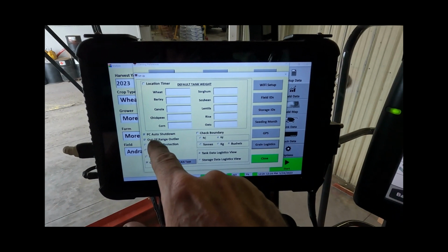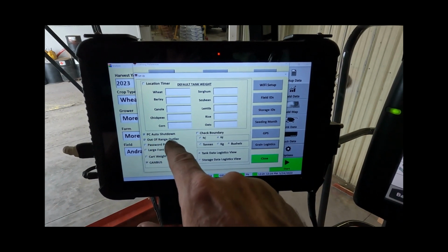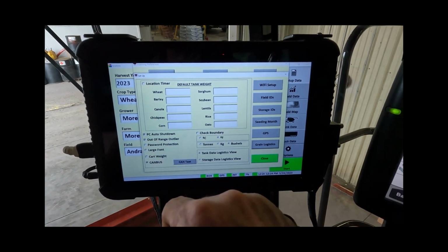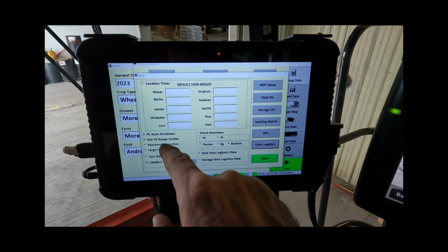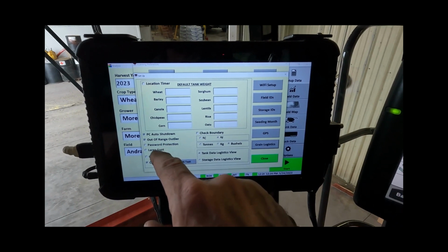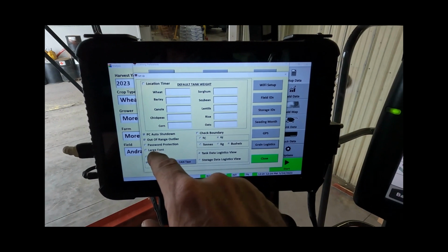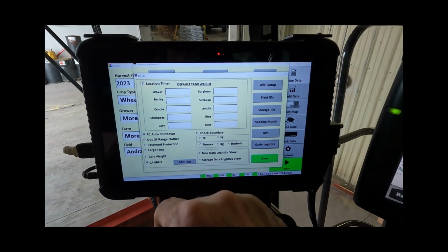This feature is used to detect when a predicted result for protein or moisture or oil is detected, and this will bring up a warning on the main run screen. These warnings are designed to notify the operator that an adjustment may be required. The adjustment may relate to a calibration issue, a probe position, or a scanning error. The CropScan screen and settings pages can be protected with a password, and also a larger font can be activated. To activate these functions, you'll need to tick these boxes.